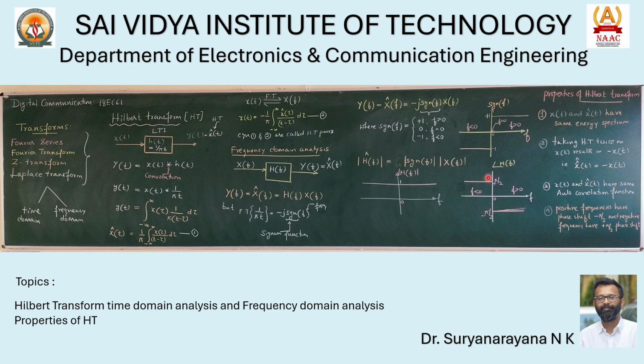If we multiply that with minus, minus into minus is plus, so we get plus 90 degree phase shift. This indicates that the Hilbert transform introduces a negative phase shift for positive frequency and a positive phase shift for negative frequency by 90 degree. So what are the properties of Hilbert transform?